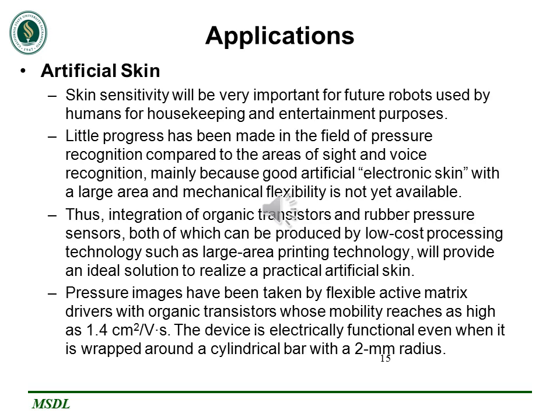available. The fabrication of a sensitive skin consisting of pressure sensors would definitely require a flexible switching matrix that cannot be realized with present silicon based electronics. But organic field effect transistors and thin film transistors can substitute for such conventional electronics because organic circuits are inherently flexible, and flexible transistors are potentially ultra low in cost even for large area.